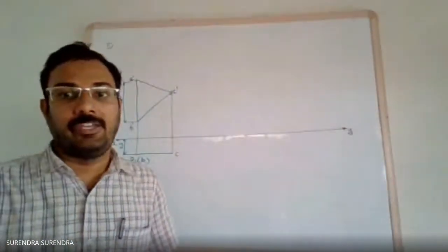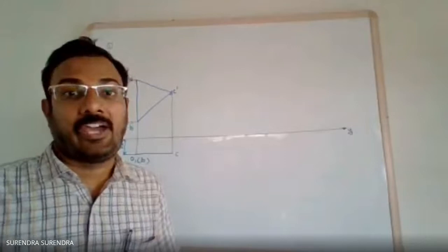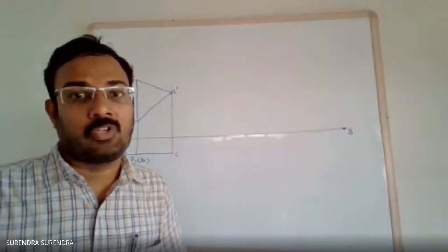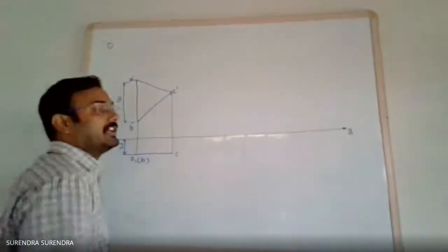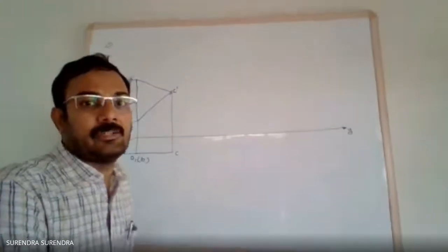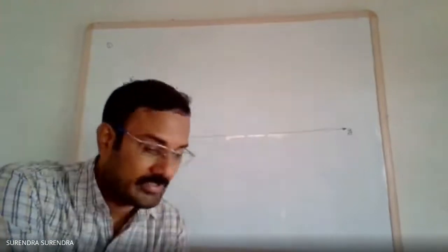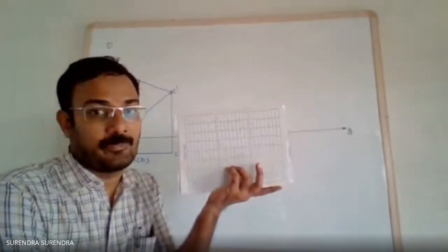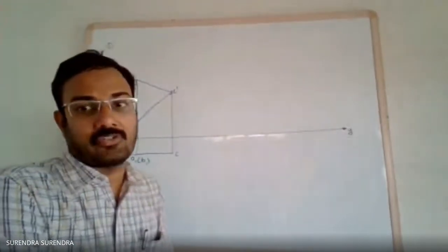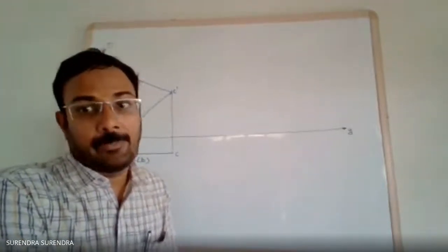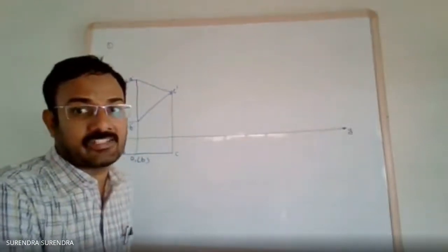And the next condition, point B. This is the point B, when one of its sides is parallel to the horizontal plane. So the initial figure has the same condition, that is, the plane is perpendicular to the horizontal plane and parallel to VP. So you can see the true shape in the front view. In all those three problems, A, B, C, we can see the true shape in the front view, but with different orientations. Now, one of its sides is parallel to HP.